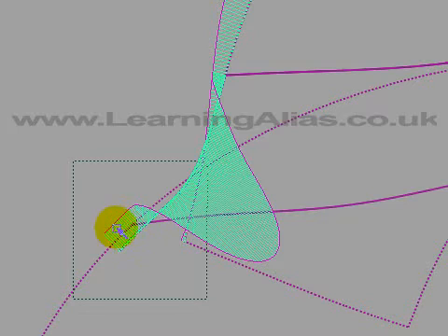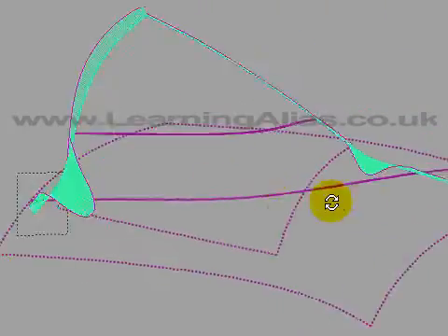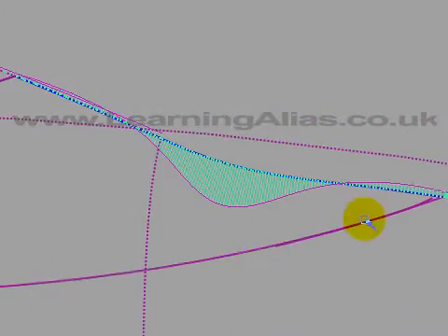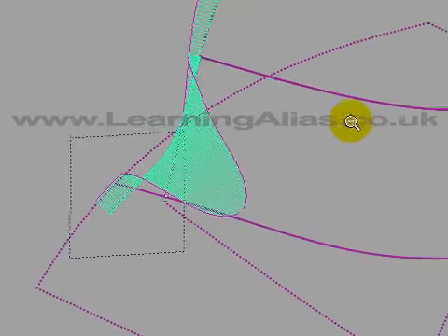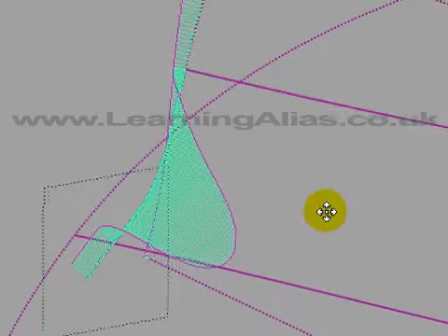This is how your curves should be looking, and you should have a feeling of G3 at both ends of the curve with a nice curvature and the peak more or less in the middle of the curve. And here, because the angles are different, we have a shallower look. And always use a construction plane to planarize your curves to, because Alias works a lot better at building patches if you have planar surfaces wherever possible.